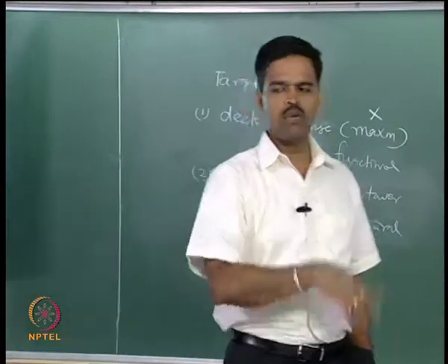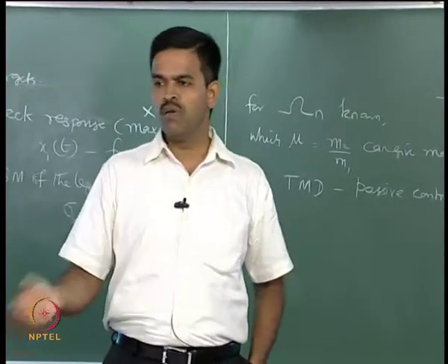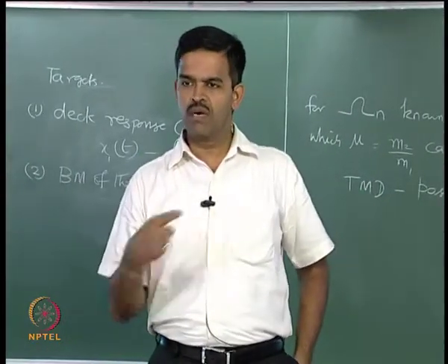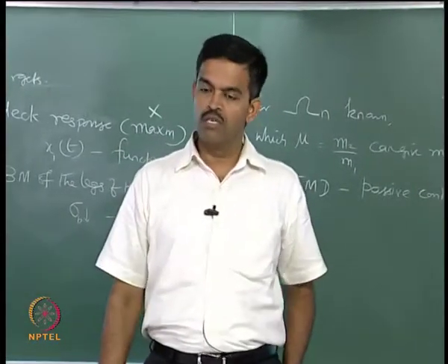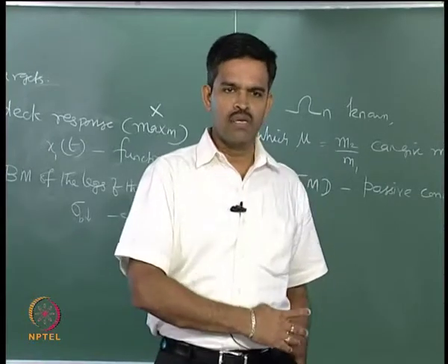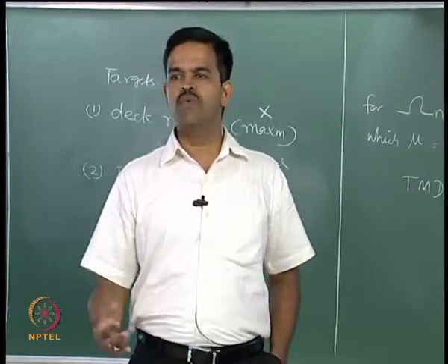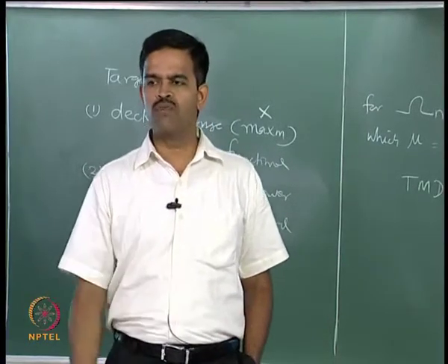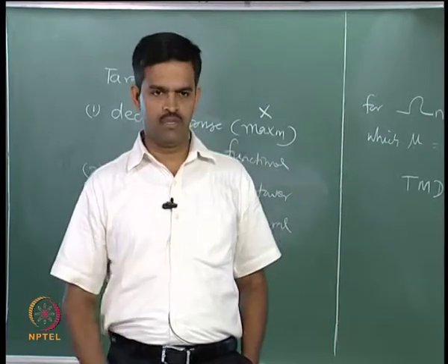So, we had a Mathieu stability study on a triangular TLP and showed that it is much more stable in specific degrees of freedom compared to a square TLP, whereas the cost saving of the new geometric form is more than about 40%. So, when you have a cost saving and you also have stability and the responses are much lower, this form is acceptable. That is how new geometric forms evolve in offshore engineering to go for deeper waters.